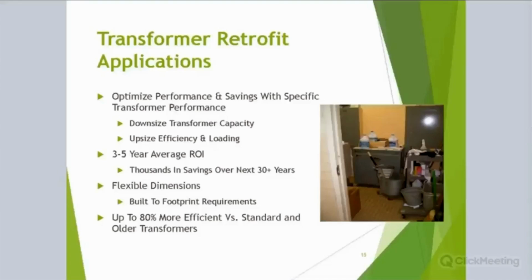You're not replacing a lamp, you're not replacing components in it. It just sits there and runs typically. So one of the things we point out is make sure that transformer is warranted for that time period. Some manufacturers will warranty transformers for 25, 30 plus years because they know what you're buying, they know what they've built, and it will last that long. If they're only supplying a 1 to 4 to 5 year warranty, be a little suspect. That transformer should last 30 to 40 years regardless.